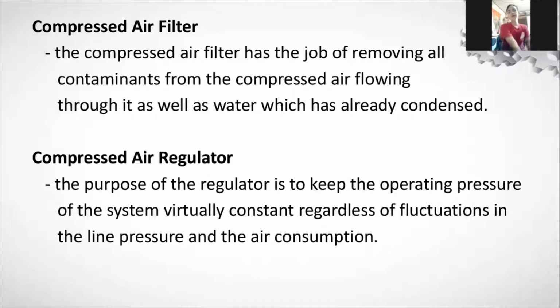So I added, we have three types of filter. General purpose, coalescing filter, vapor removal filter. General purpose used to remove water and particles. Coalescing filter used to remove oil. Vapor removal filter used to remove oil vapor and odor.